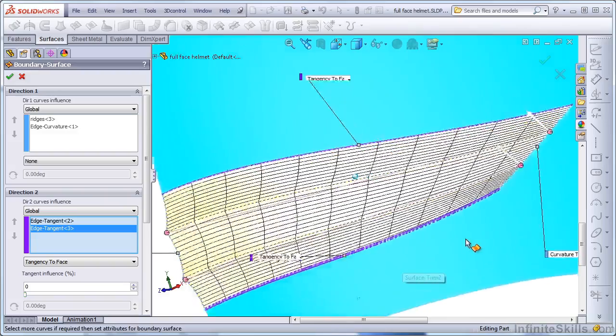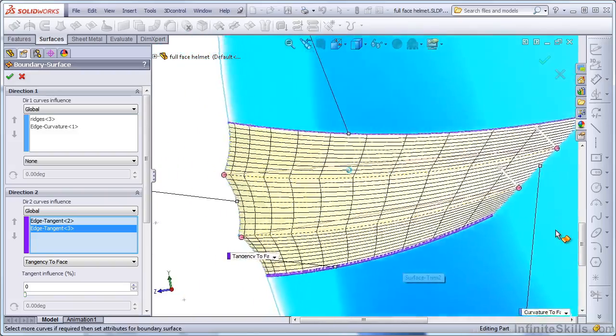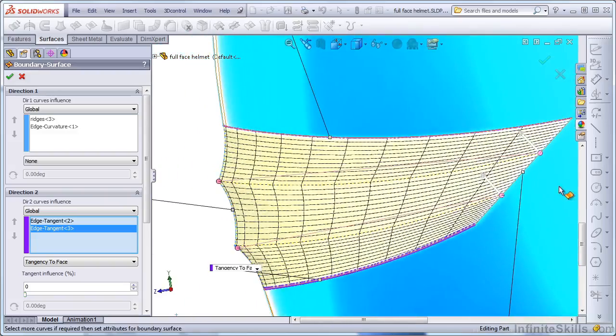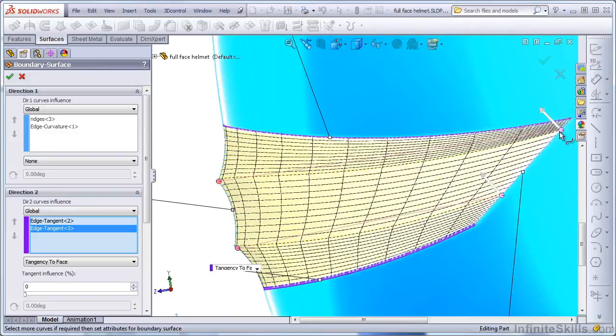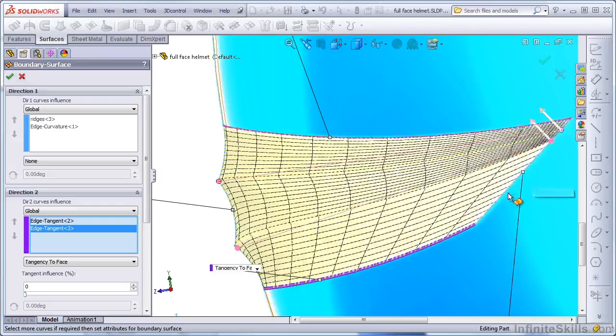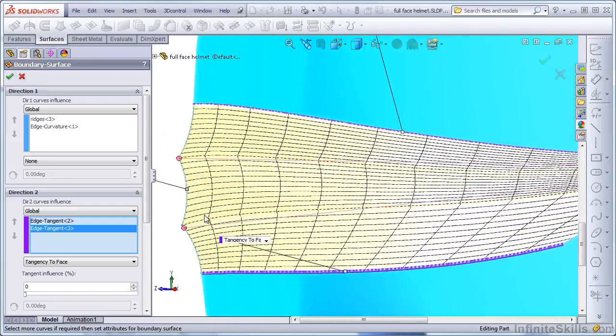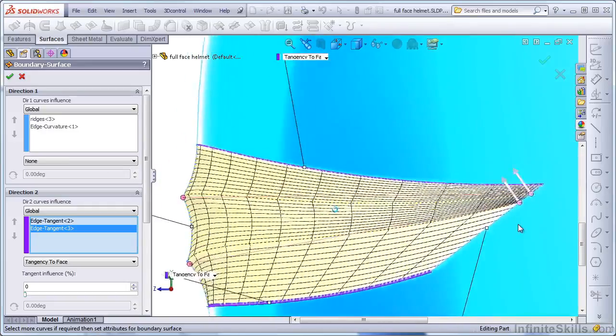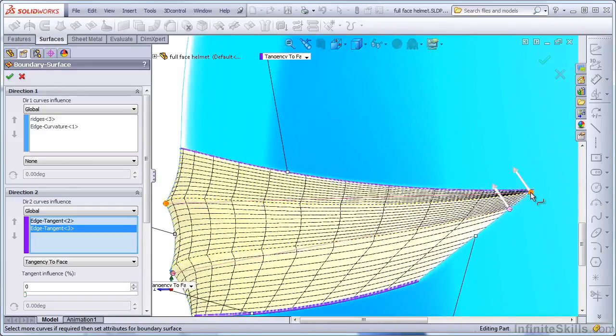Now I want to show you some of the things that can happen if you try to push a connector too far. You take this and push it up here, and then take this one and push it up right behind it. Very often you'll get a little pucker in the part right down about this area. Let's try to push it even farther.